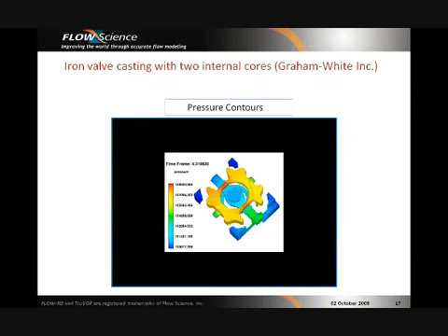Now let's take a look at the pressure contours. Shown here is animation. You can notice the higher pressure buildup on the saddle core. It is clear that the T core builds up pressure closer to the prints, so it can be vented through the prints. However, the saddle core has higher pressure showing on its upper surface that could present the risk of blowing into the metal.